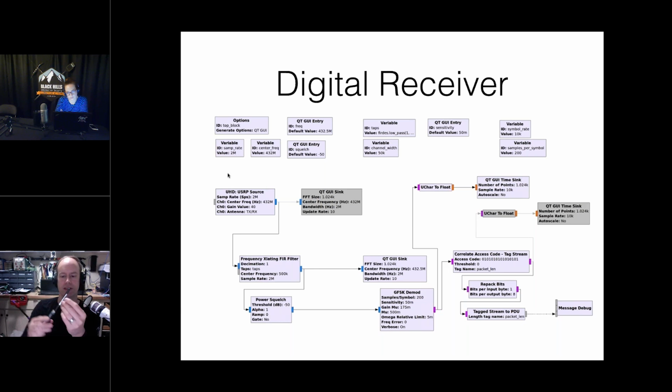The other thing you can do, though, because they are remarkably affordable, you can see this little guy here, which I've got this cheap label maker label on. This is a 433 megahertz antenna, and it's nice sometimes when you know you're working with a specific band of frequencies not to have to worry about the retraction and the extension, but rather just to get something that is always optimized for the frequency in question.